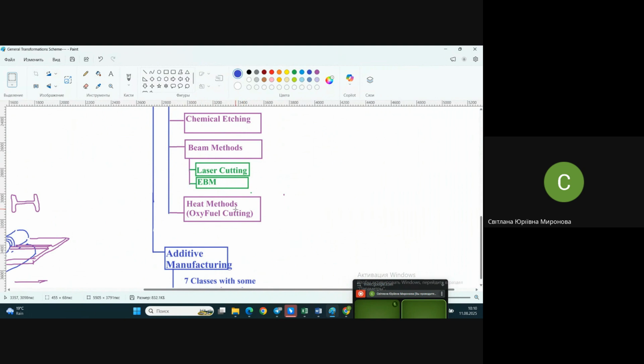What you have melted, you may either leave for solidification or use an additional channel with injected air with a high velocity. You just blow it out from the place of melting, and due to this you have cuts, even like this.